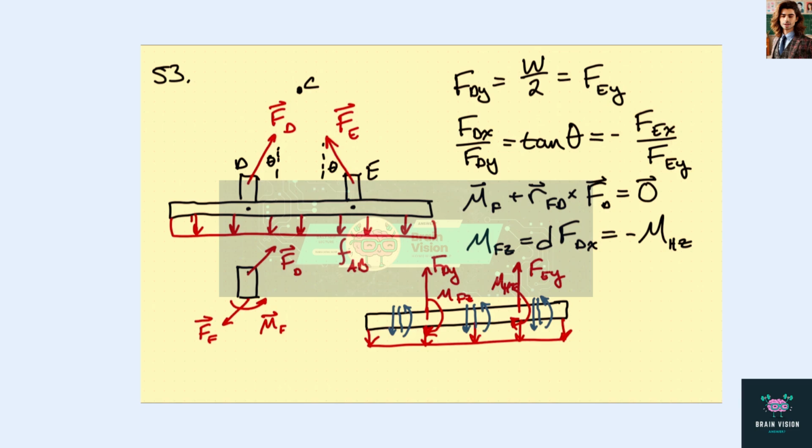We can then figure out what the bending moments are, and they're going to be equal and opposite. And so we have a bending moment from the horizontal components of these. So a bending moment like this and a bending moment like this. And so those act here. So we have the vertical components acting as point loads, and then the horizontal components acting as point moments at these two points on our beam. And then we have the weight, we're assuming, is distributed uniformly over the beam.